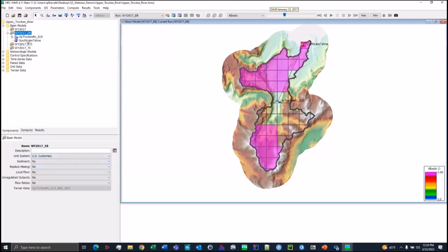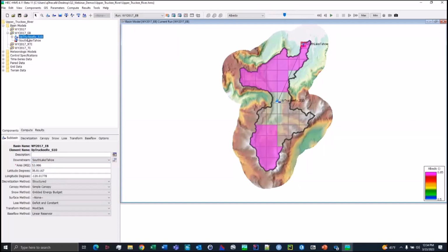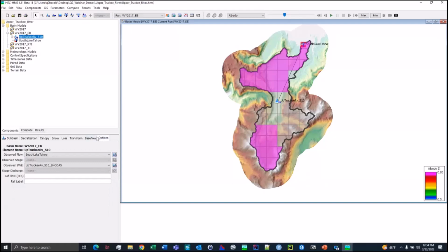In addition to linking something like a SNOTEL station or an on-the-ground SWE station observation, we're often working in watersheds where we want to calibrate to SWE throughout the modeling domain. If you're not in one of the few Western states that has SNOTEL stations, or if you don't have a snow course nearby, you might be using off-the-shelf gridded products to calibrate for SWE. A couple of the common ones that we use are SNODAS, the Snow Data Assimilation System, and the University of Arizona SWE data set. And what you can do is extract a subbasin average time series of SWE